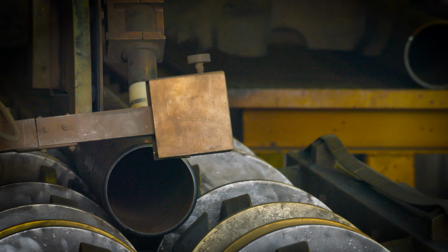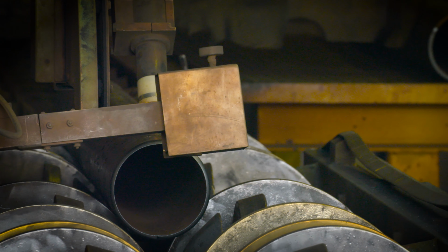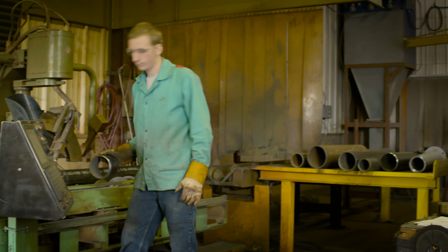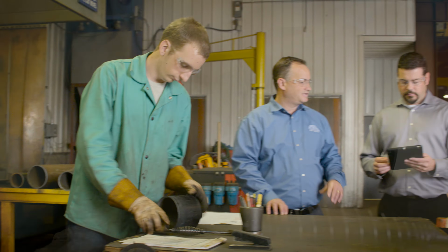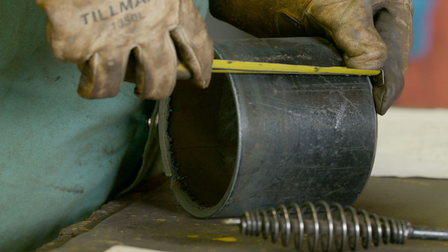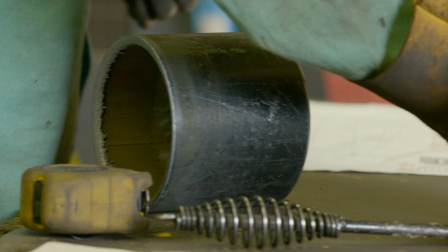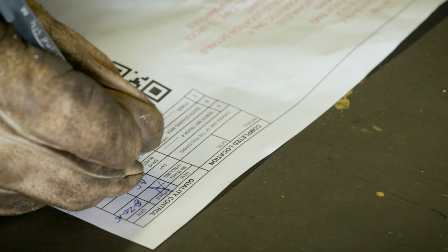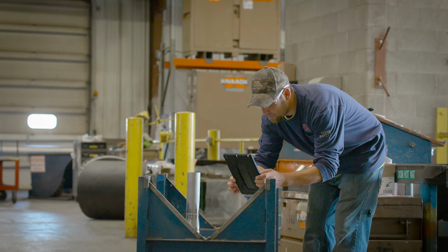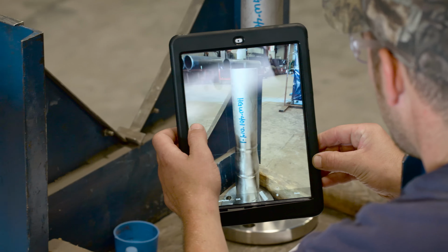Fittings and pipe is gathered together, then goes through the tacking process, through the welding process. Each stage of that is captured with BIM 360 Field. We use that record to verify that each quality component has been met. So each individual in the process step is signing off on a portion of the drawing. Once we pass through that final stage, we're free to load it upon the truck and ship to the site.